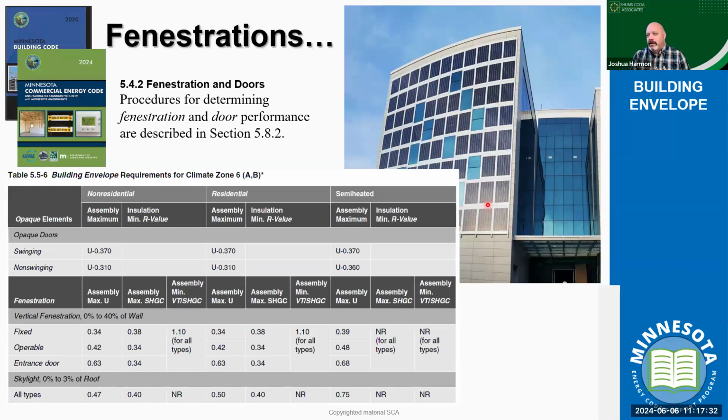Now, what this one did is they integrated some solar panels into their windows. But when we have a lot of light coming into the building, then if we don't have the appropriate daylight sensing controls, then we're spending energy that we didn't need to because we've got adequate lighting. Now the question is whether trade-offs are still allowed within this new code.